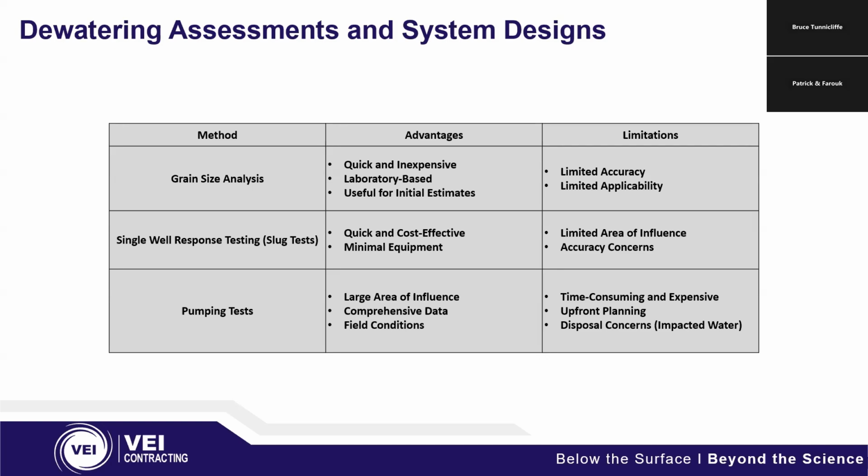The limitation for it is it's somewhat time consuming and it can be expensive because you usually have to install 1 or 2 pumping wells to carry out this test. There's a lot of upfront planning from that drilling and then the data logger placement and data management. And if you're dealing with an impacted site, you sometimes have to think of disposal concerns because these generate water.